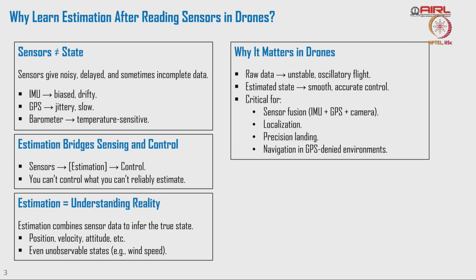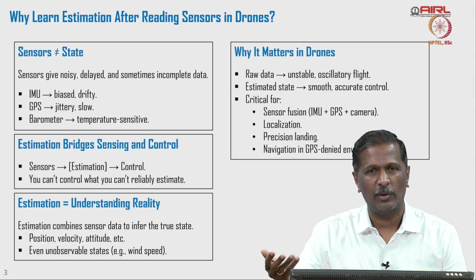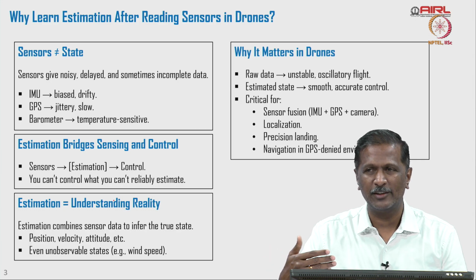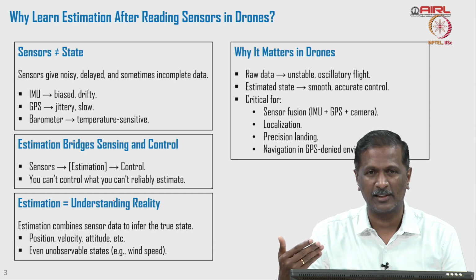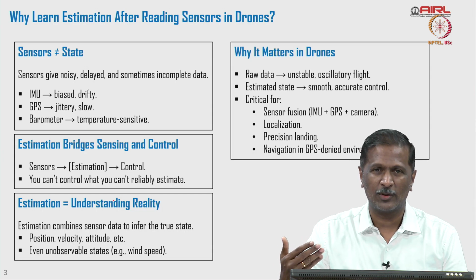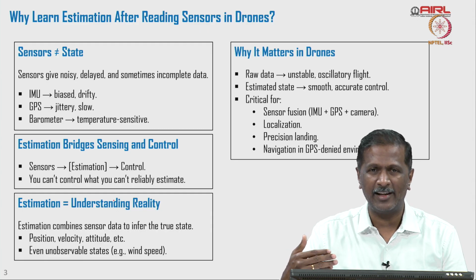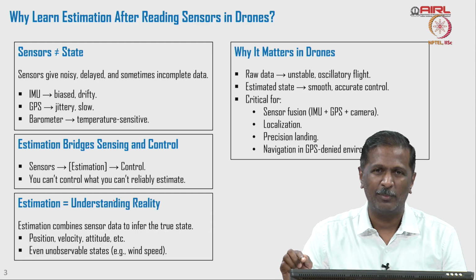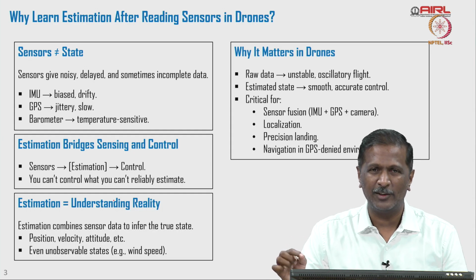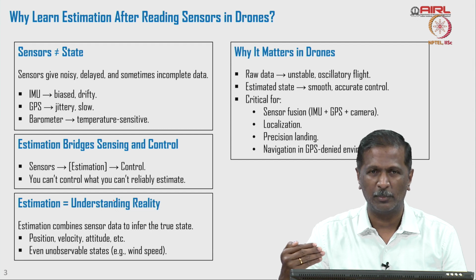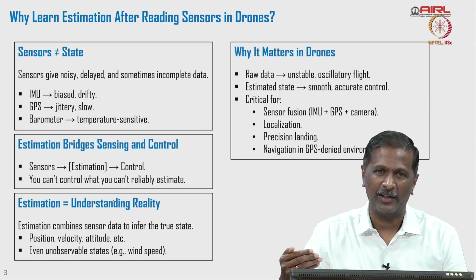For example, in a later part of the course, we will talk about obstacle avoidance. For obstacle avoidance, you need to know where the obstacle is, what is the shape of the obstacle, what is the relative distance to the obstacle, what is the relative velocity, so that the drone has the compute capability to generate a local path and follow the local path. Once you generate a local path, you need to follow the path accurately, right? So there are factors we need to take into picture. So detection or knowing the obstacle location is also critical for us to do obstacle avoidance.